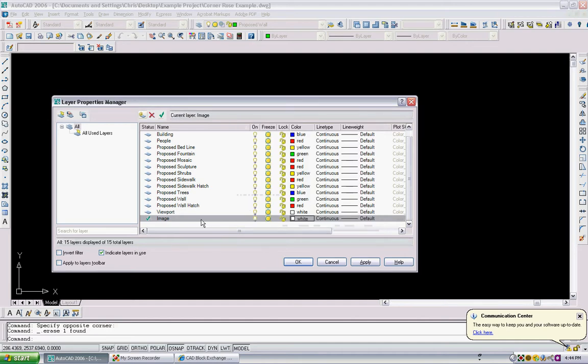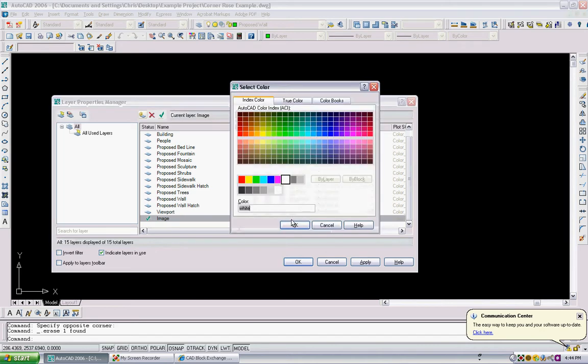Now for pen settings, some of the sophomores were selecting colors to draw in. For LDI at least, I don't know about the other ones, and if you make your own, you can pick any of these colors, but for the LDI pen setting that I'm giving you all, they only respond to these index colors here, these major colors. So for instance, if you have a red here and you put it on the LDI 2007 settings, it's going to print this color. It's not going to print black. So in order to have your drawing print black and with line thicknesses, you have to use these colors for your pen settings. Alright, so keep that in mind.